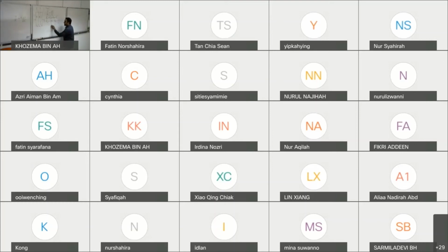So that is the first thing that I'd like to show you. The second thing is that we know that Q is equal to QA is equal to QB is equal to QC because it is steady state. Now let's say I would like to know the temperature here, T2. The question usually will give me T1 and T4, but I would like to find the value of T2. So you can use this.